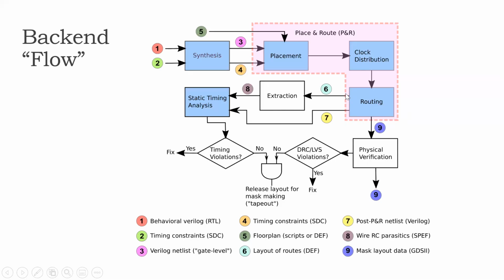So all the nets and the layout are exported in the form of DEF, the same file format that is used for the floorplan input. It can also be used for getting all the details of all the individual wires or the nets in the layout, which metal layers they are in. The entire geometrical picture of each net is captured in the DEF. So that's one export. The second thing that comes out of the routing at the end of place and route